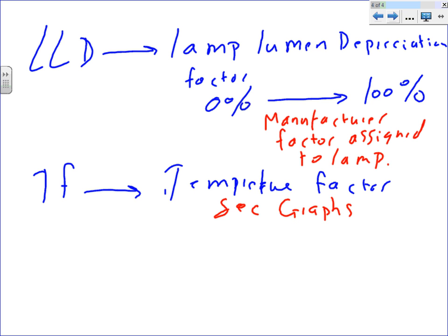So if it's 3000 at 40 degrees Fahrenheit, you get exactly 3000 lumens. If you increase it to plus 60, the percentage of mean rated lumen is going to go up, and you can see at a certain point it starts going down. As the temperature goes higher, it goes up for a limit, and then it goes down again. If the temperature is low, you can see that fluorescent light at minus 20, you don't get a whole lot of lumens out of it.